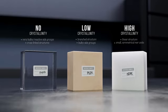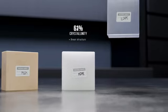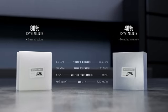Polymers with a high degree of crystallinity tend to be stiffer, stronger, and have a higher melting point than more amorphous polymers, because close packing creates stronger intermolecular forces. High-density polyethylene has linear chains with minimal branching, with crystallinity of around 80%, whereas low-density polyethylene has a branched structure resulting in much lower crystallinity of around 40%. The difference in crystallinity explains why the two materials have significant differences in stiffness, strength, melting temperature, and density, despite being made from the same repeating mer unit.